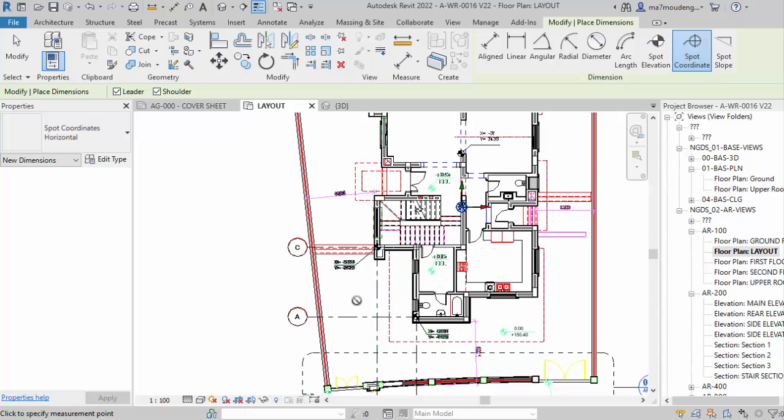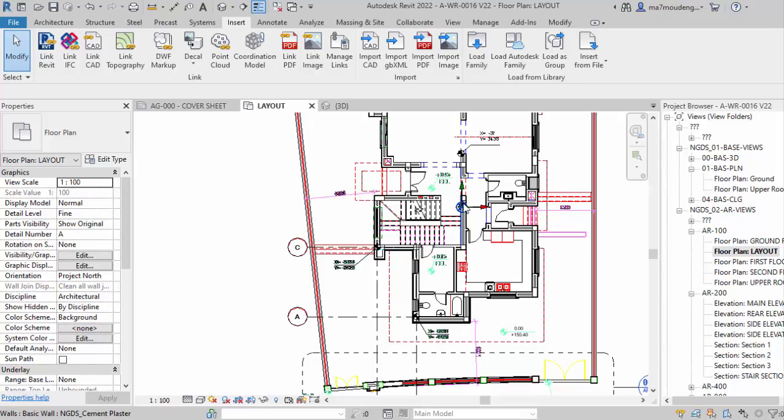And this is actually the main point of the false northing and false easting: to avoid negative values. So if you can set your project base point in the far left corner of your project, it's also a best practice and a good hint for you in the future.